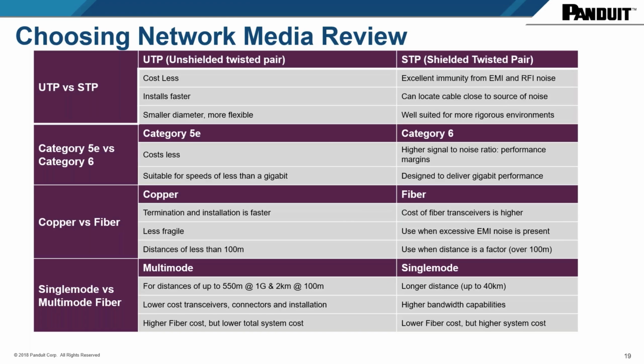When you look at the fiber, having single mode versus multi-mode also is determined by how far you could run these cables. So multi-mode fiber, for instance, could take you up to 2 kilometers. When you go single mode, and that's a very expensive type of cable, you could go to 40 kilometers. So again, the determination of when to use shielded versus unshielded, copper versus fiber, a 5E versus 6 versus 6A, all of these different specs have to be taken into consideration.